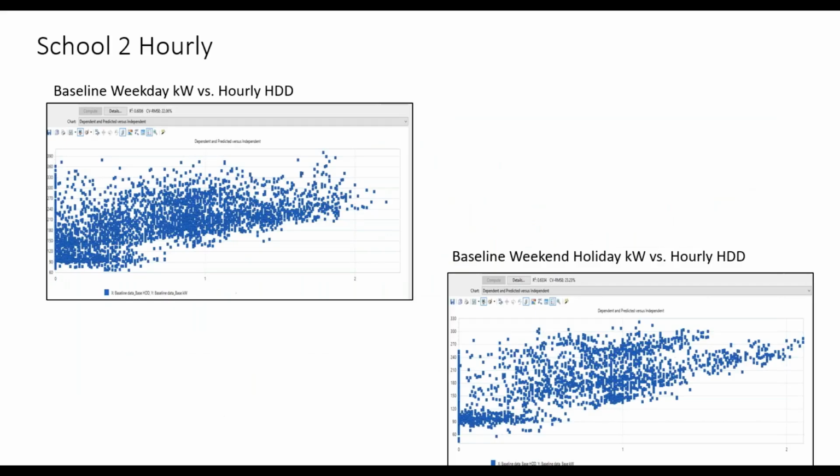And these are the graphs for the hourly. Talk about scatter. The thing that I really like about weekly, weekly is the one I always like the most, but weekly and monthly have a smoothing effect. Let's say you have forklifts in your building and you charge them, but you don't always charge them at the same hour. There's so much randomness that happens in a building. And having longer intervals kind of smooths that randomness out. I think that's why you end up with these better fits.